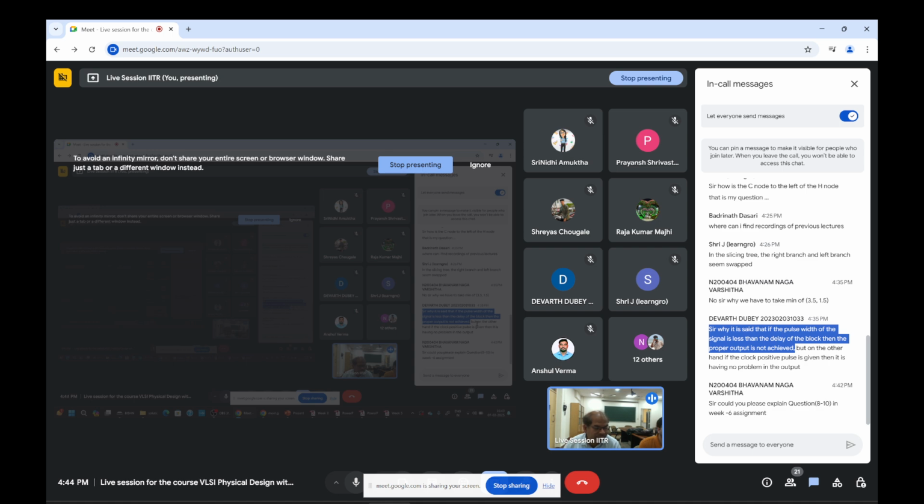But in the case of a small clock pulse, if your input is changing during that time, the small-width pulse acts as a gate to your transmission gate, which is open for a short interval of time. During that time, if the setup time of the latch is satisfied, then the signal at the input of the latch will propagate to the output.